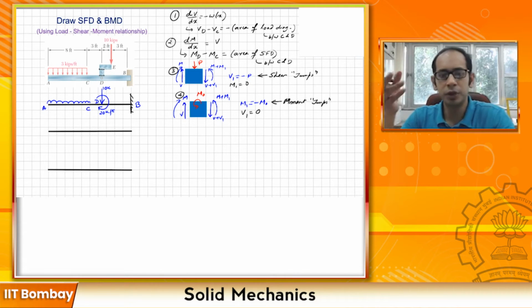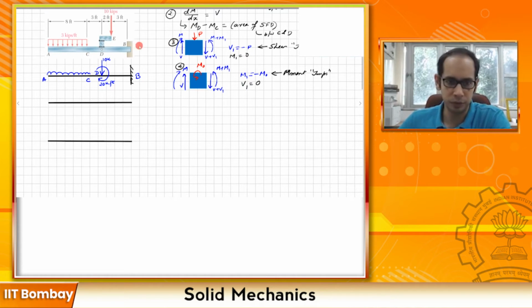Now this is important, it was important to write all of this, because the loading that you have over here has all these types of loads. So here, as I said, I have done the equivalent beam with the equivalent loads. Now I'm going to draw the shear force diagram for this one and the bending moment diagram here.